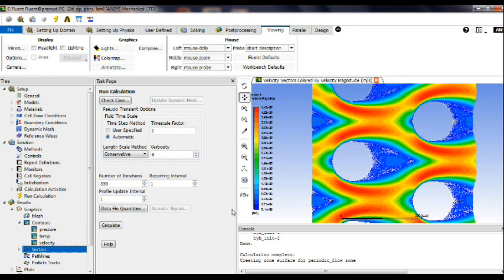The tube bank configuration lent itself to the use of a hybrid mesh, as we had seen in the meshing, where we have quadrilateral cells around the tubes and triangular elsewhere. You can also check other possibilities by changing the Reynolds number, flow rate, and the geometry dimensions.